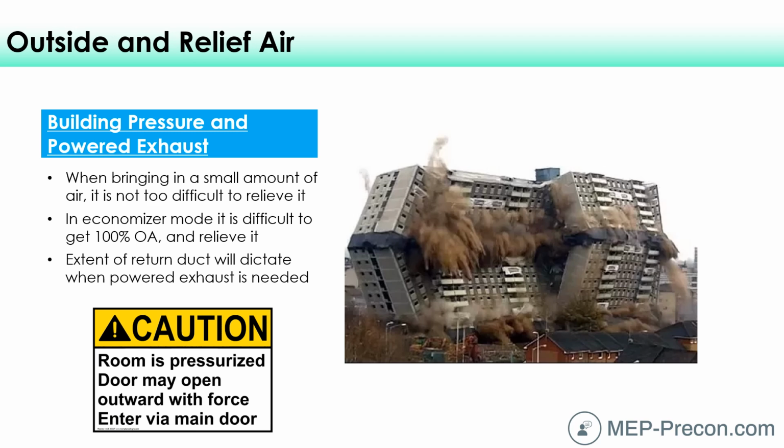You see, in normal occupied mode, outside of economizer, you bring in some minimal amount of outside air, just enough that it meets the code requirements for the number of occupants that are in the space and to prevent it from getting too stuffy and so forth. So that might be, I don't know, somewhere around 20% of your total supply air that's being supplied to your space. But in an economizer, 100% of that air that's being supplied by that fan from the unit is outside air.